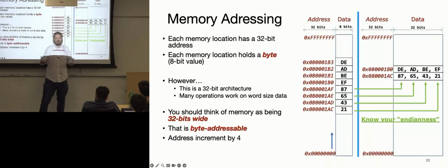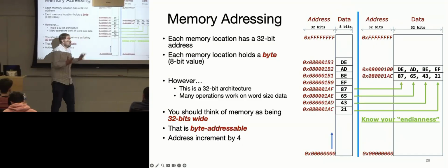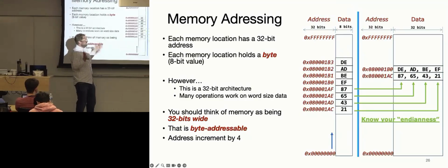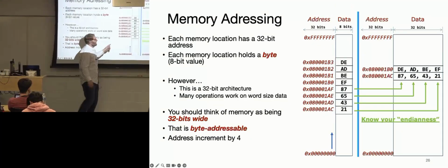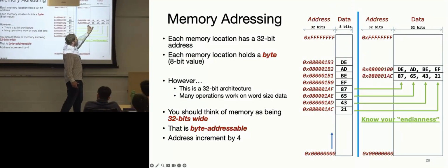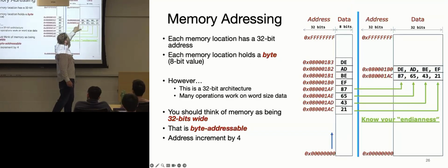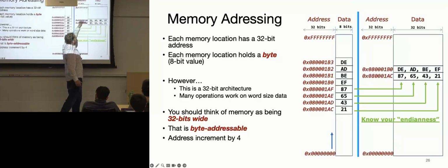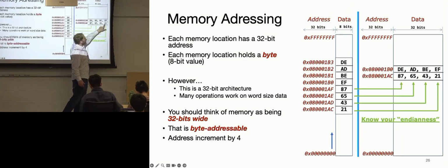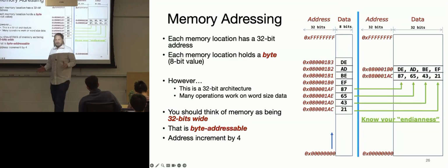Most of the operations you'll do are actually 32-bit operations. Because your buses are that wide and your whole system is set up for that, you're just going to be storing and loading 32-bit words. You just have to make sure you're doing it at an index of 4 so that you're getting the data out. However, you have the opportunity, if you choose to, to store bytes and half words. Does that make sense?